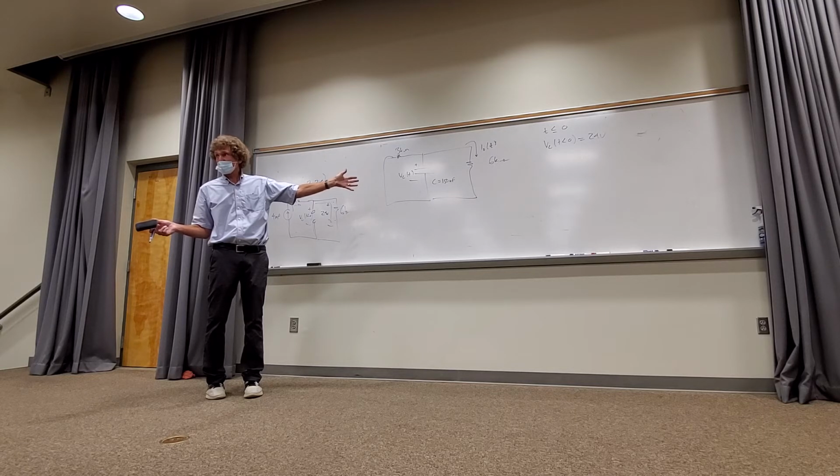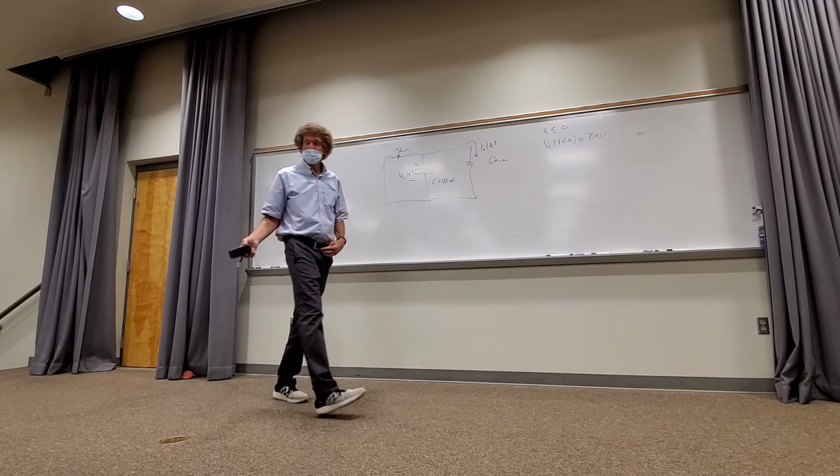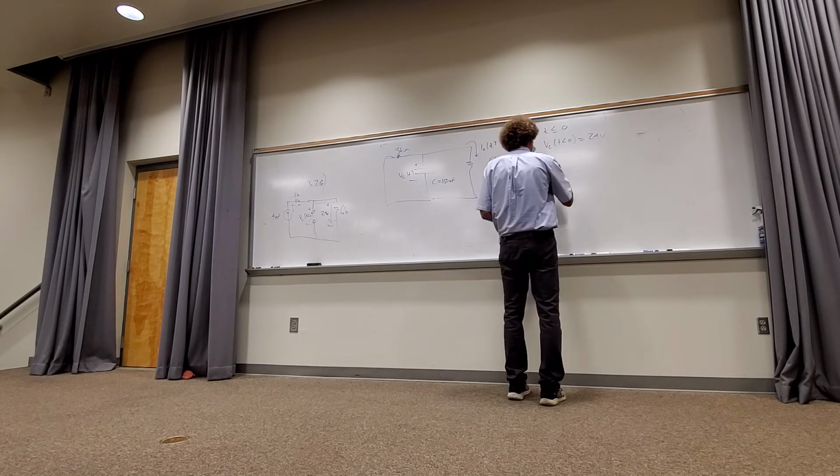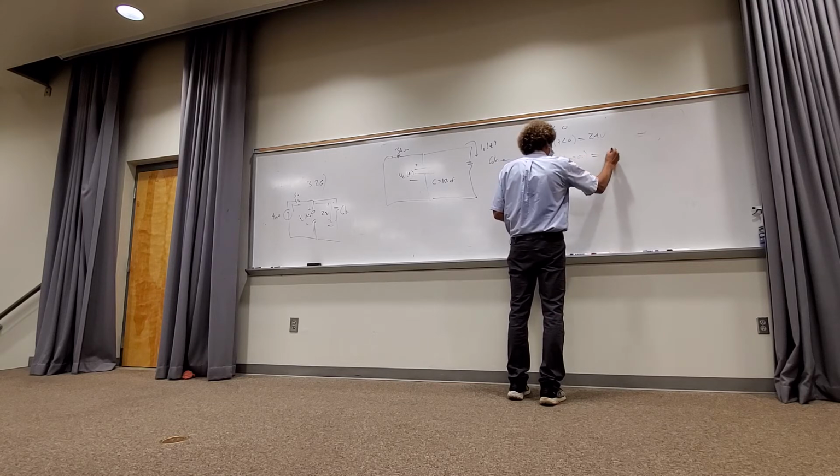Are there any sources there? Any voltage or current sources left? Where does the voltage go to, class? It's going to 0. You all see that? Sure. So that means the voltage across the capacitor as t goes to infinity is 0.